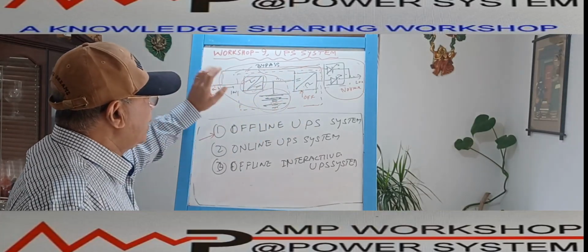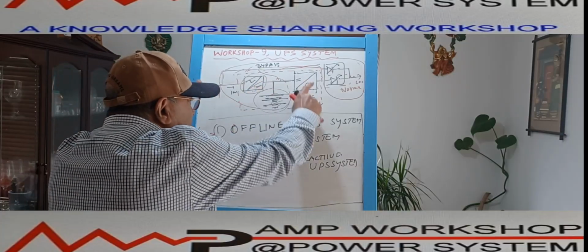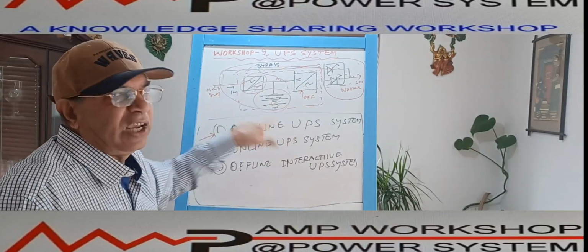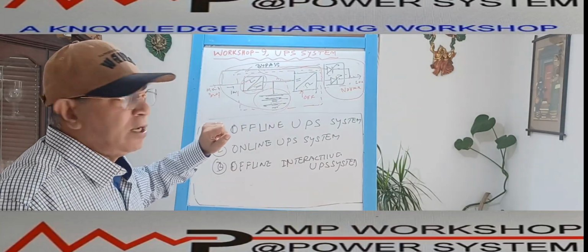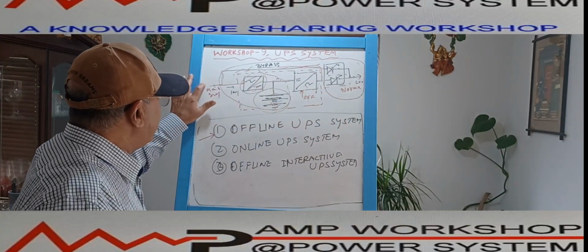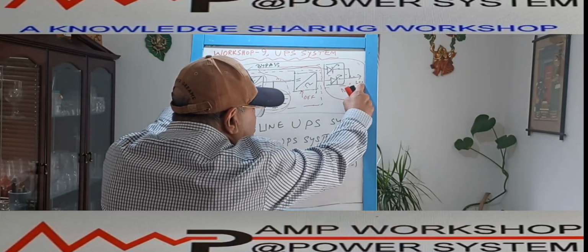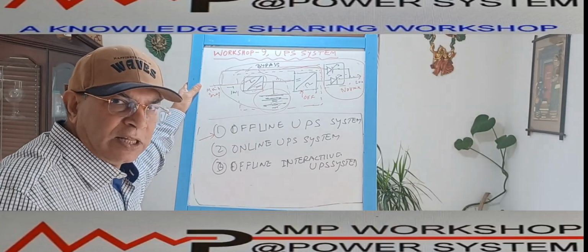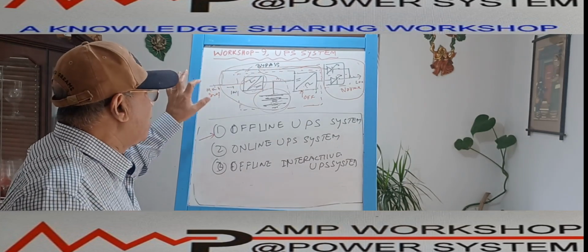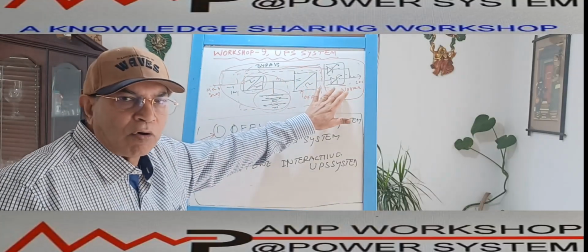And second point, as these UPS systems are all solid state devices, there is a lot of power consumption inside, which is emitted from the system as heat. That is the loss of energy. So regarding system efficiency and the electric bill, when the main supply runs through the UPS system, although the output voltage profile, frequency, and all will be good, the loss inside the UPS system will be supplied by the main supply. That will increase the electric bill of the consumer.